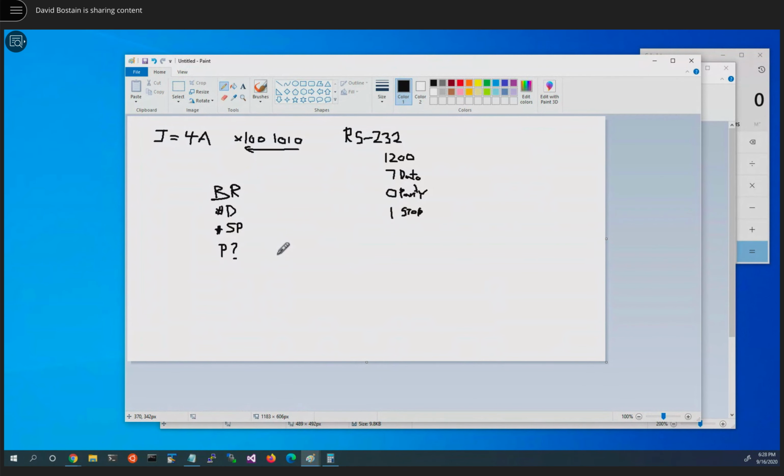But once we've agreed on that, and as long as we honor those conventions, we should be able to reliably send bits of data. So if I send a character to you, I've basically sent you 8, or really 7, bits of entropy, which you can assume was better than me sending you 100 pieces of data in parallel, because all I have to do is send you close to 120 characters or something, and you will have seen the same amount of data. And as long as the asynchronous protocol is fast enough, then I don't have the problem of maintaining 100 lines next to each other on a circuit board, which cause their own problems. Very hard to route that many wires.